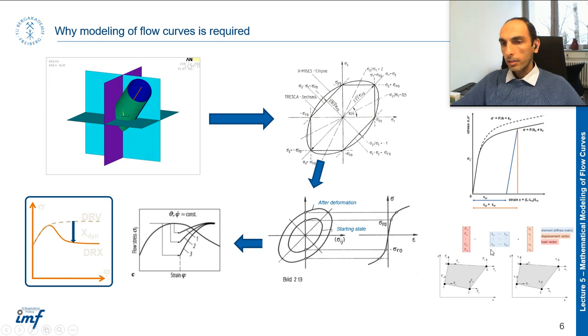And so what should we put here for the plastic deformation? Exactly what interconnects the applied force and the deformation together is the flow stress curve. So what we need for connecting the strain and stress together is the flow stress diagram, of course in the plastic area.